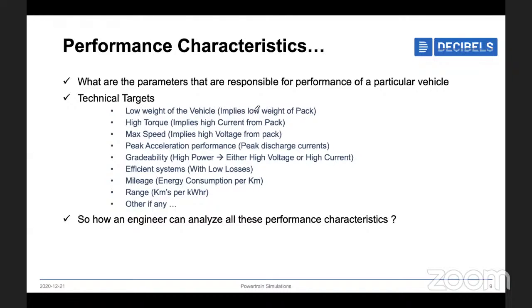When you want initial accelerations to be very high, your pack current should be very high. Also maximum speeds, which again depend upon how much voltage you are getting from the battery pack. Peak acceleration performance depends upon peak discharge currents. And gradability. Unfortunately, in the formula race car events we won't be having any gradability, so we can give it as 0 degrees.